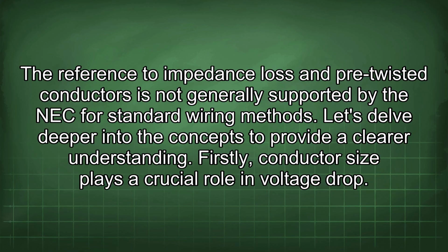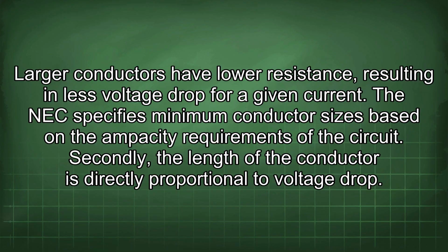Firstly, conductor size plays a crucial role in voltage drop. Larger conductors have lower resistance, resulting in less voltage drop for a given current. The NEC specifies minimum conductor sizes based on the ampacity requirements of the circuit.